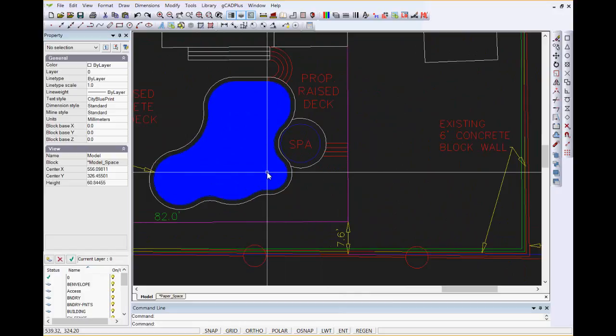So it really doesn't matter whether you take the trouble to make the LCD file or just use DXF files. Your base information will be brought in. You keep it isolated, and so you can update base information really quickly, easily and efficiently. What you don't want to be doing is finding that the base information has changed and you have to go through and pick individual entities. You want to be able to pick that base information as one item.